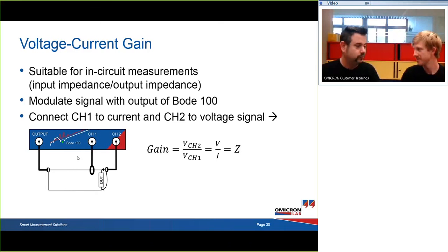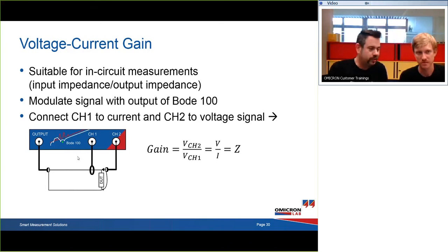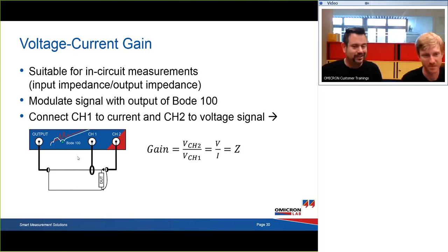Yeah, absolutely. In fact, the current injector came into existence because I learned that someone was directly connecting the output of a power supply to the output of the Bode 100 and performing a one-port measurement. I said, come on, if you go above 3 or 4 volts, you possibly kill the output op-amp of the Bode 100. And so the current injector came into existence.